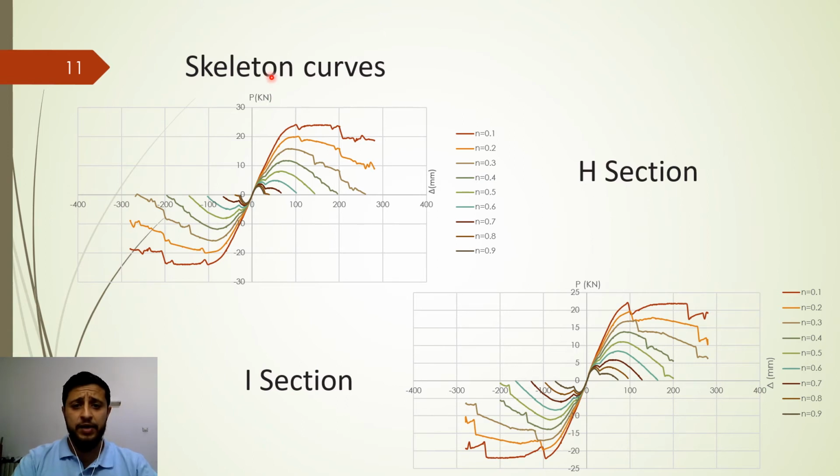A skeleton curve can be obtained by connecting the peak point of each cycle of the lateral load displacement curves. A skeleton curve is used to measure ductility, strength, and deformation capacity of specimens, and for studying the elastoplastic cyclic response. It can be found that these columns behave likewise in the linear stage. However, there are obvious stiffness degradation differences between these curves in the non-linear stage. The lateral load decreases after yielding of the specimen.